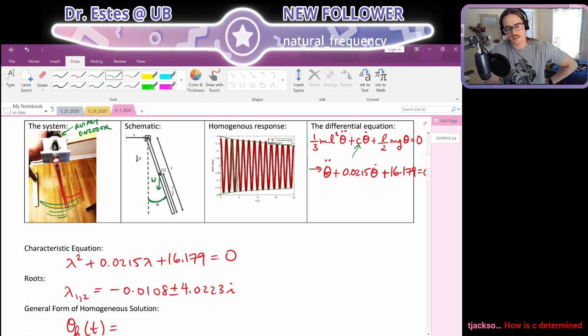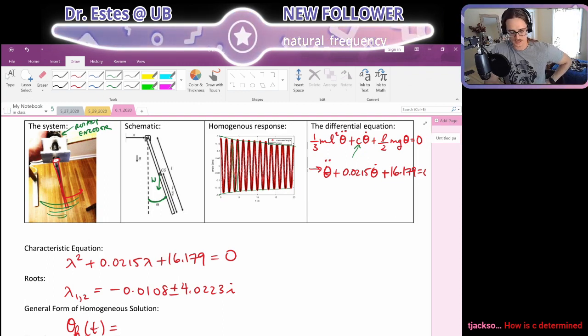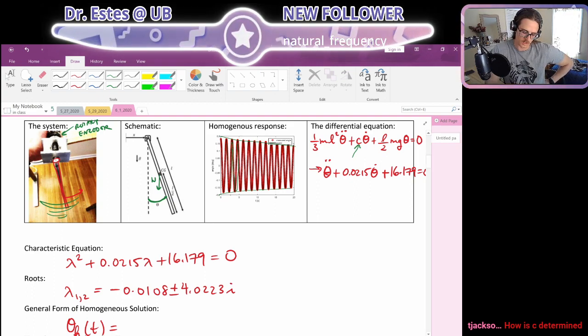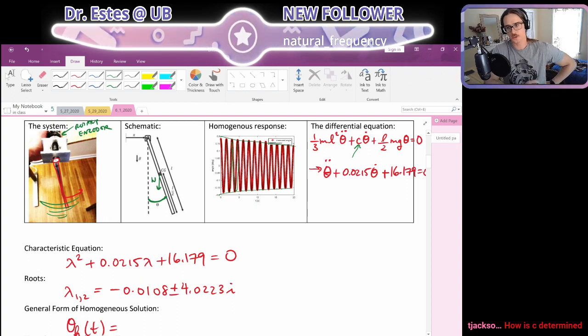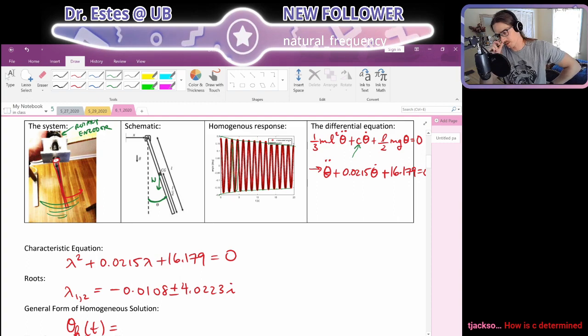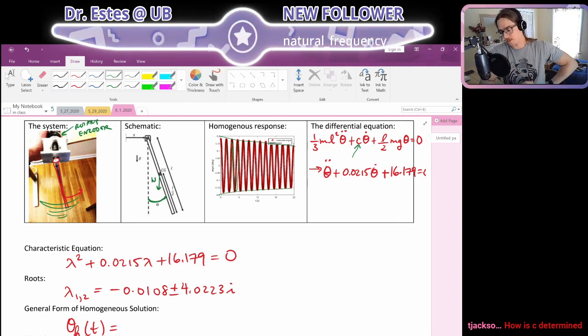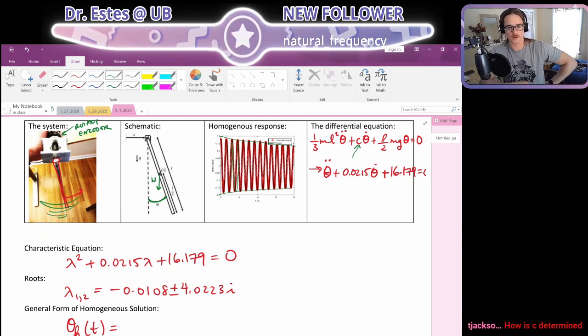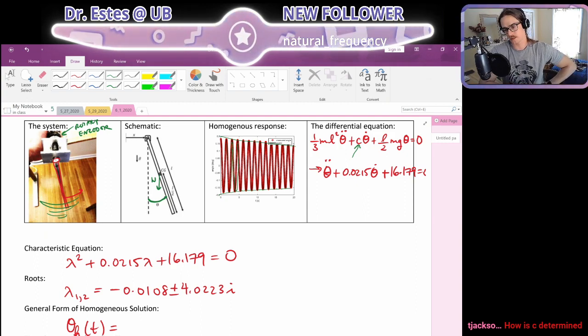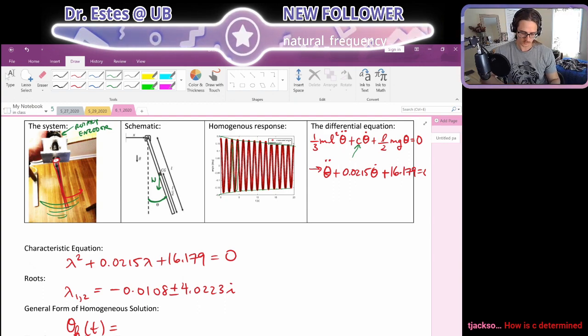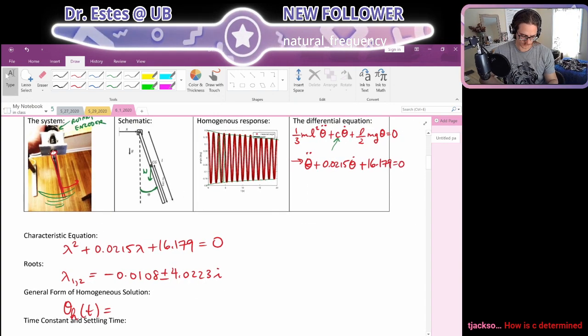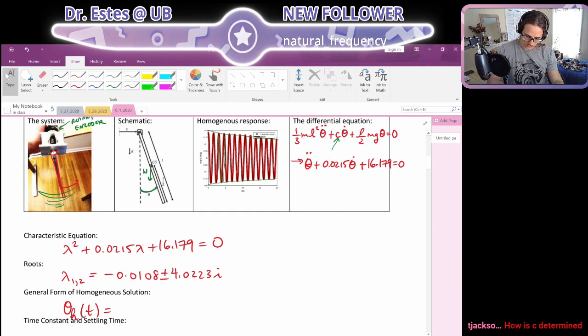And there's a technique called the logarithmic decrement method. Basically what that does, it looks at how quickly the peaks decay over time, and it lets you backtrack what's called the damping ratio of the system. And we're going to talk about the damping ratio today. So I experimentally determined the damping ratio, and then from there I determined what C is. Fantastic question.